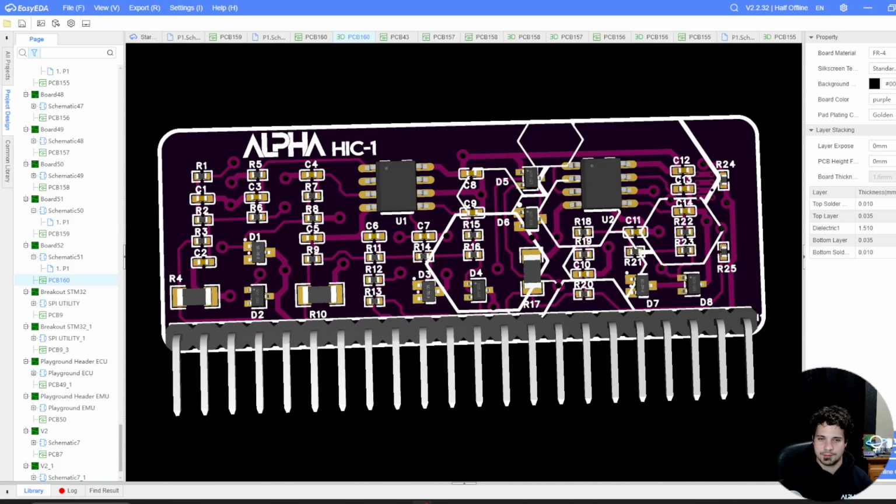So there's just 3 inputs. They come through, it handles the crank signals, cleans it up, and sends them back to a Schmitt trigger. And Schmitt triggers are pretty cool. I use them on my Pi PLC, which is my elevator controller that I designed. And essentially, a Schmitt trigger takes a signal that goes high, low, high, low, high, low, and it cleans it up to where it's either high or it's low. There's none of the oscillating that happens in between. So the idea of this board right here is simply to clean up a circuit and amplify the outputs to make them work.